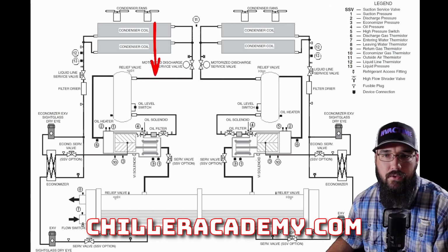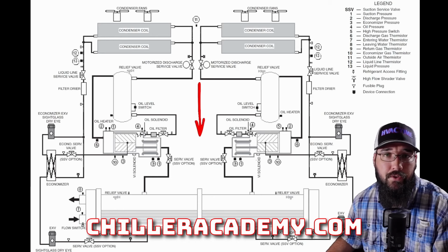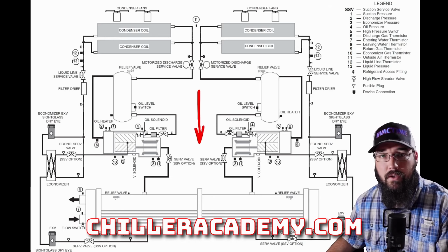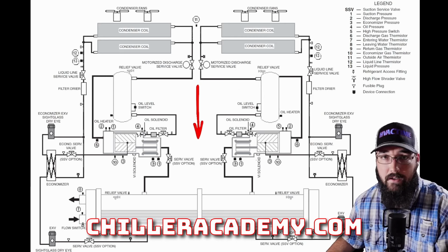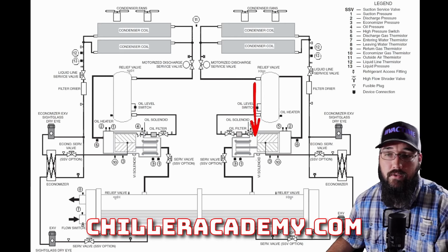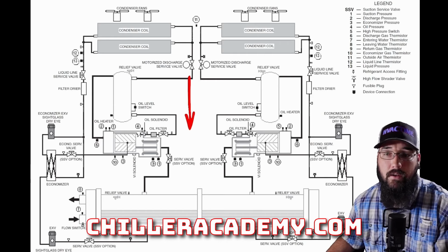And don't get too bamboozled by all the piping and stuff going on here. There's a lot that happens inside of these machines. We're going to break all this down. I want you to focus on how the compressors are being controlled in terms of staging to load and unload them correctly. You read Carrier, so this schematic is out of a 30XV manual.